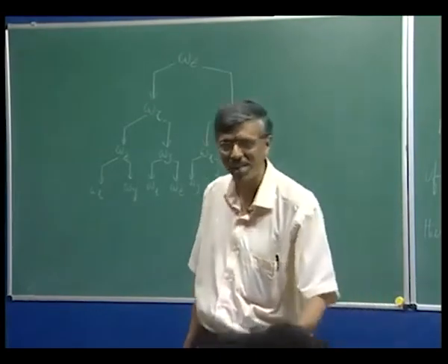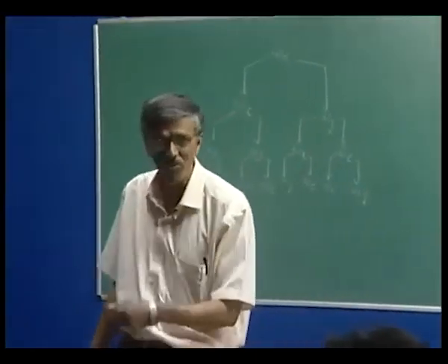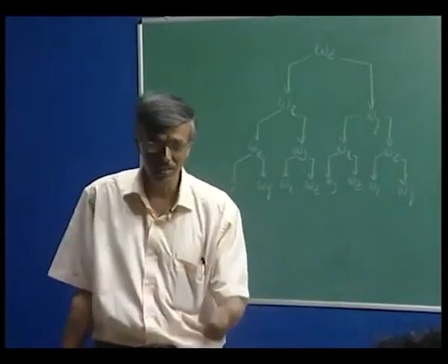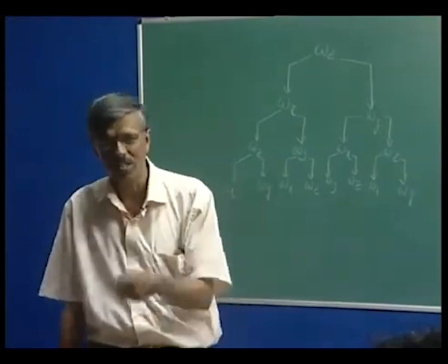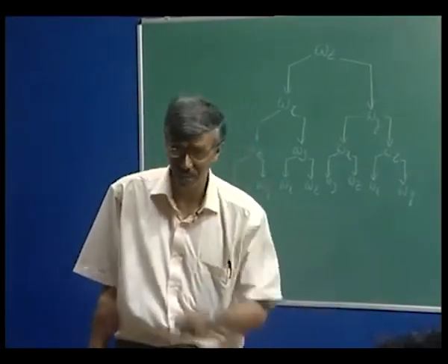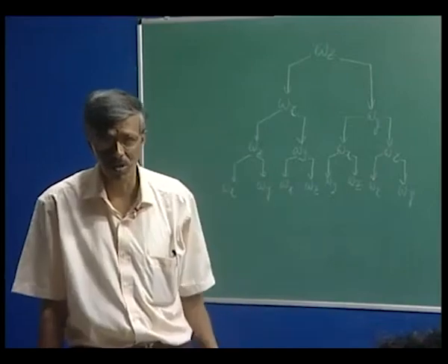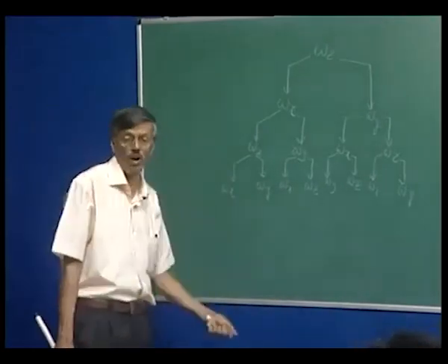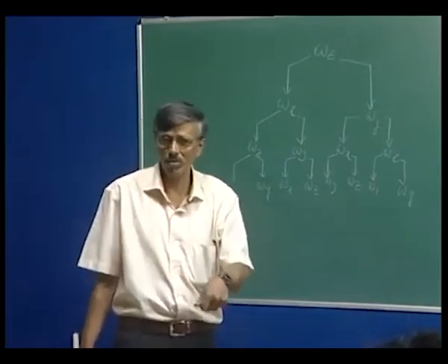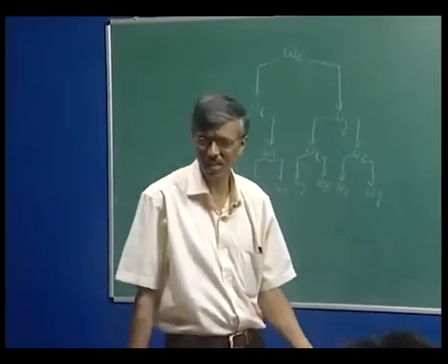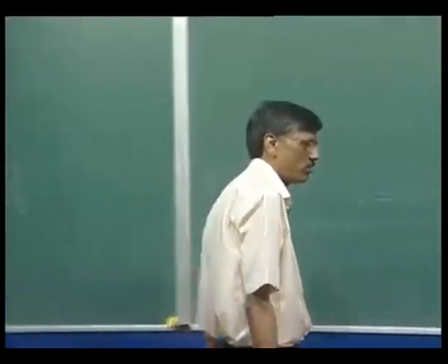Modeling is always helped once you know what is happening. For example, previously we saw in the time averaged equation how Reynolds stress was correlated with the mean strain rate, and that helped us develop a turbulence model. So, in LES also we make use of the fact that at the subgrid scale we have isotropy. That is a very hopeful sign and good news.